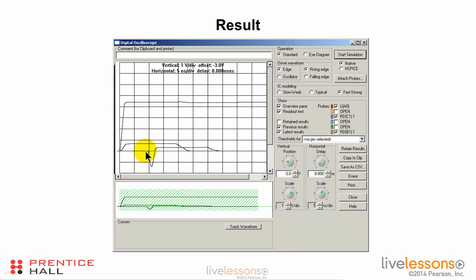It shows up at the far end of the victim trace 10 nanoseconds later. That's the 10 nanosecond propagation time through the victim trace. And the backward crosstalk signal shows up at the far end of the victim trace at the same time. So it is showing up here. It's going to be 20 nanoseconds wide. So we go 5, 10, 15, 20 nanoseconds plus a rise time. So there's the backward crosstalk signal at the far end of the victim trace.